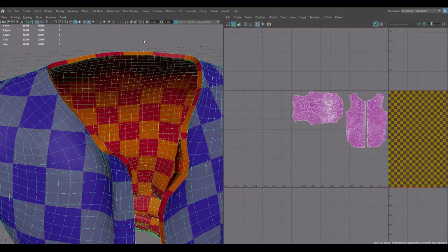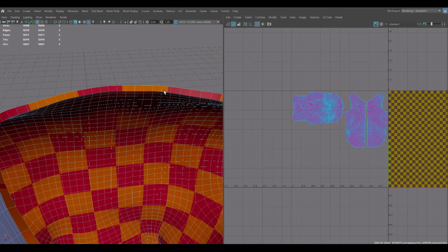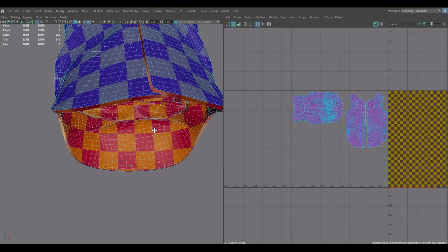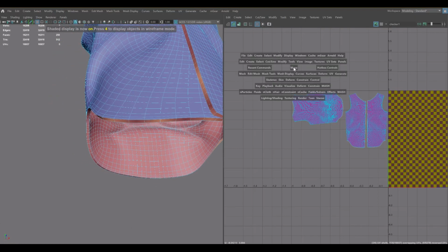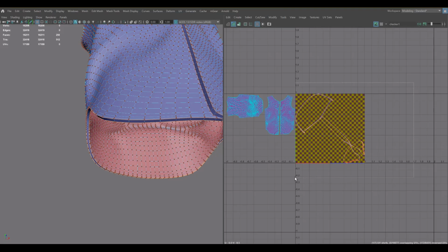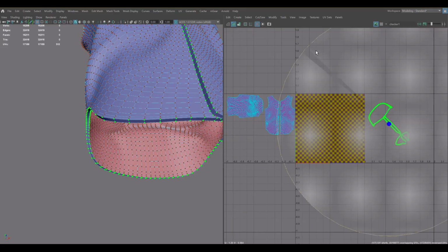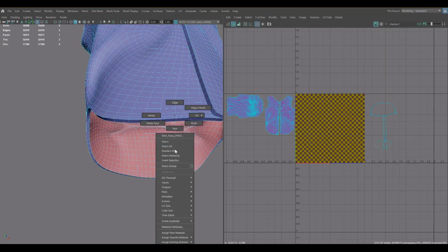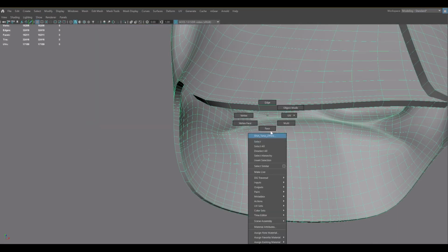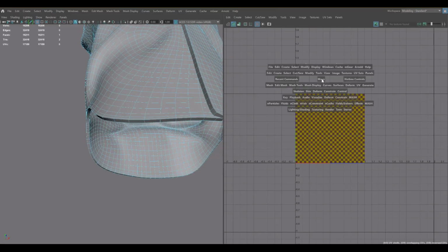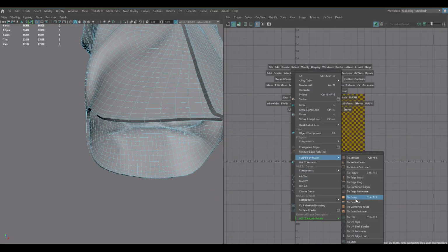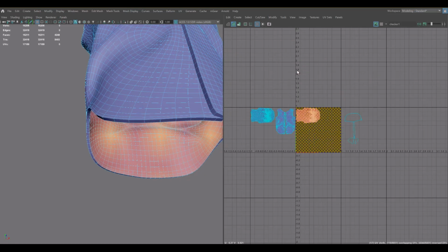Now, in the process of extruding, we've added this edge, which we can easily isolate, at least in Maya. You would grab a face and then double click on the next, and because that's a continuous loop, it'll select all those faces. And I think for demonstration purposes, that will be good enough. We could unitize those, we could straighten them out, but not needed right now. And then that will make it easier to grab these faces and select UV shell and just shunt those over to the right.